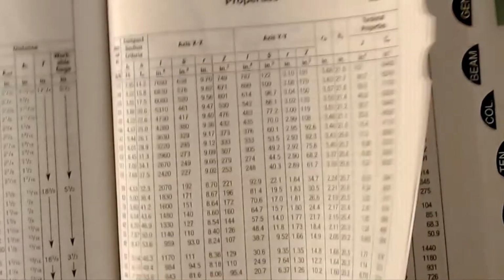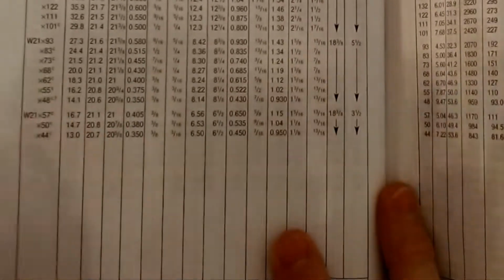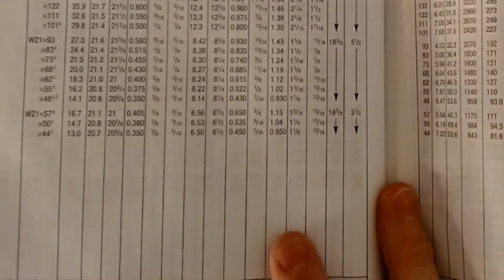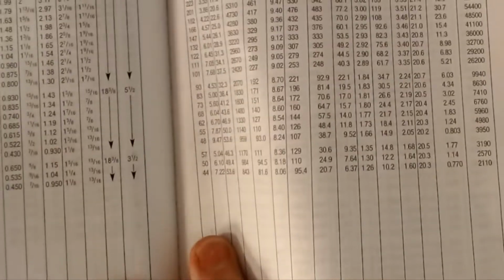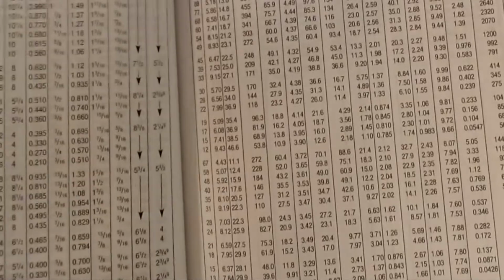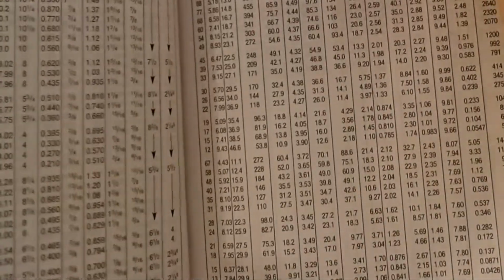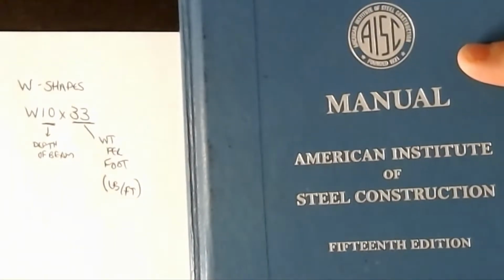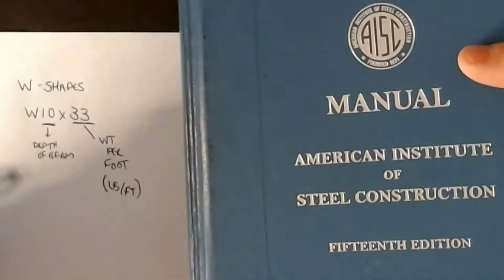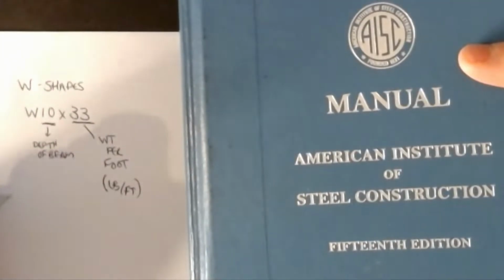So, we can flip over to some of the bigger sizes. If we start to look, here we've got W21, so it's just a matter of finding where you are and then reading off the section properties. And so you'll be doing this a lot, playing around in this table 1. So that's our W shape, and that's the way these are listed and labeled here. You'll see some other shapes in there as well.